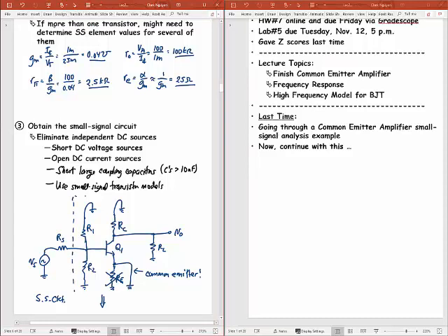Right, this is going to be more of the amplifier, and I'm going to go all the way out to resistor RL. So in the dotted box is the actual amplifier that includes the R1, R2, RC, and RE associated with biasing up that transistor. This RL is the load that we're trying to drive. This RS and that VS is the Thevenin equivalent for the source that's driving this.